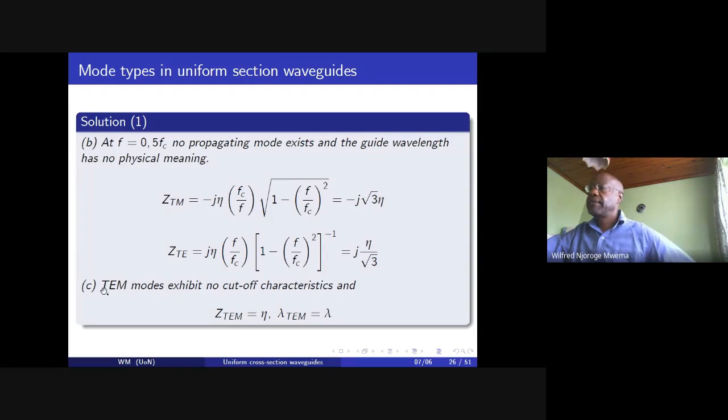And the TEM modes will exhibit no cutoff frequency or cutoff characteristics, and usually for a waveguide, the TEM modes don't exist on that guide, unless at very high frequencies such that the walls of the guide are very far apart compared to the wavelength of that signal. So this one is purely to show how TEM modes would behave, but not in that guide.